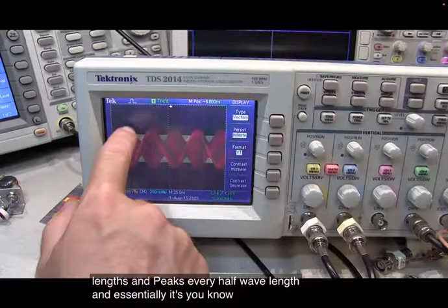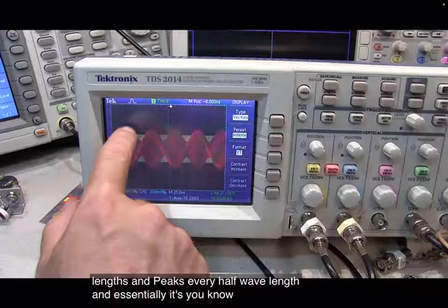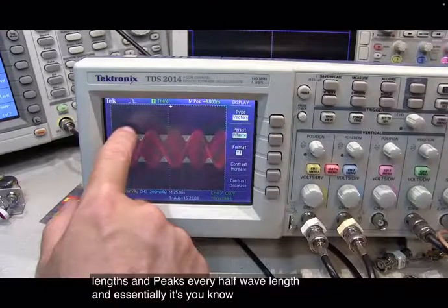So just like this, the wave's going up and down, the wave's moving, but this x-axis here, if you want to think about it, is like the transmission line. Okay, so it's pretty much like that. So if you measured it right there, you would never get a voltage higher than that point, right? It's going up and down, it's moving, but it will never go above that point. But if you measured it right there, the voltage will go all the way up to that point. In other words, your voltage on the transmission line depends on where you are on the transmission line.